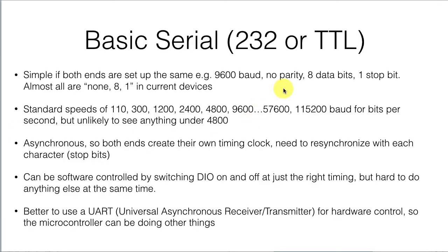Building on that, we're still using basic serial transmission, and that's actually what's going in and out of your Arduino and up to your computer. Big advantage, it's simple as long as you've somehow managed to communicate and get both ends set up the same way. If you've messed up with 9600 versus 115,200 between your settings in your sketch and the settings on the serial monitor, you've already seen this kind of problem in action. You've got to get that coordinated.